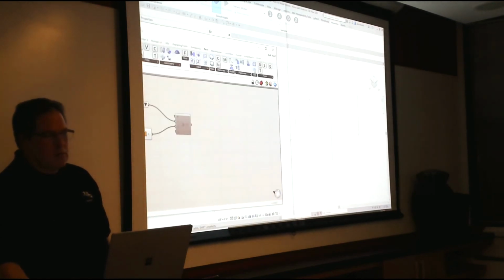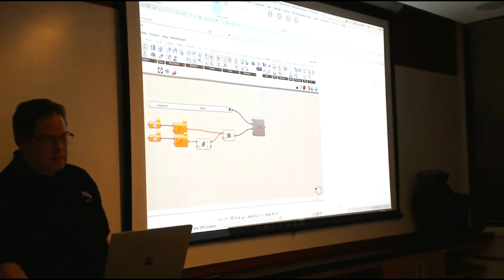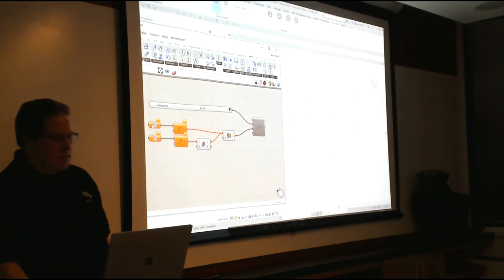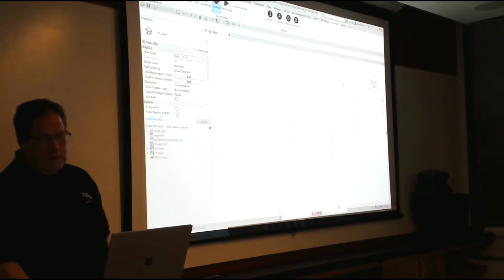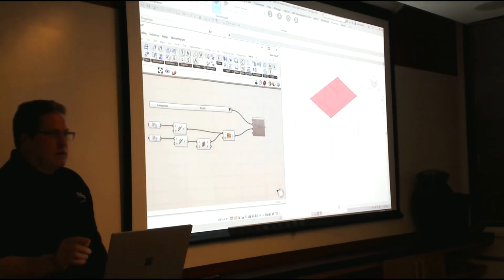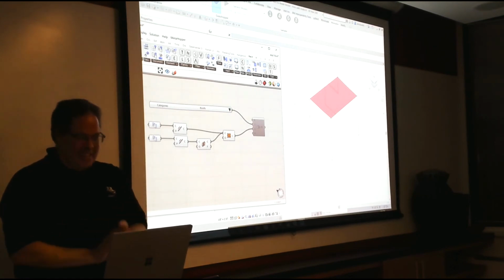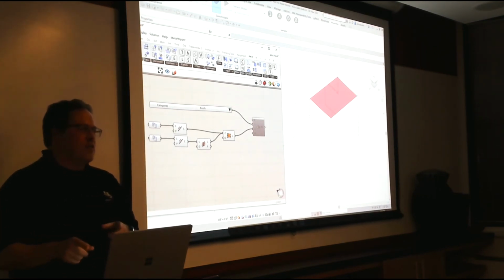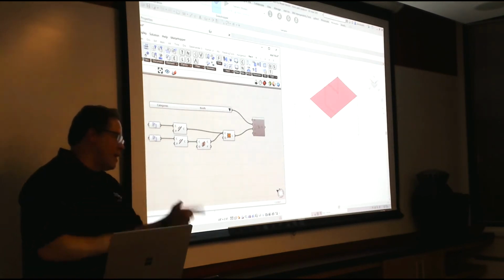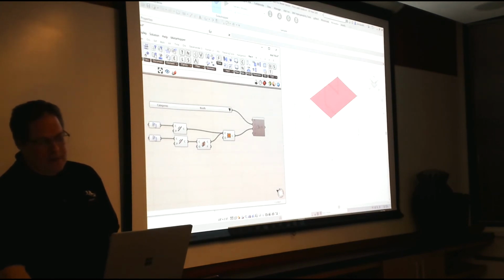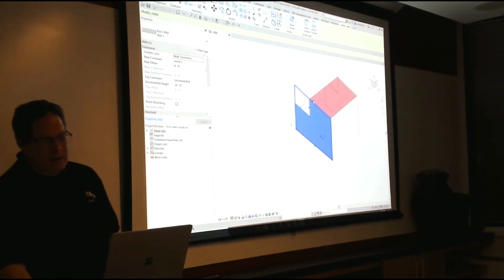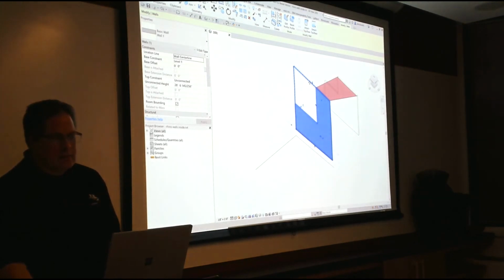All right, so we have Grasshopper running in Revit, which is what we originally talked about at the start of tonight. What's interesting here is that instead of having Rhino objects, I have Revit objects. So I'm going to say set one Revit edge. I'll pick that. Come here, set one Revit edge. Pick that. Oh no! Yeah! Whoever noticed that right off the bat. Impressive, yeah. So we have a lofted surface from Grasshopper previewing in Revit based on all edges. Right? Grasshopper, as usual, is dynamic, right? So I edit the wall and the lofted surface updates. Okay, so this is Grasshopper drawing Grasshopper geometry in Revit.